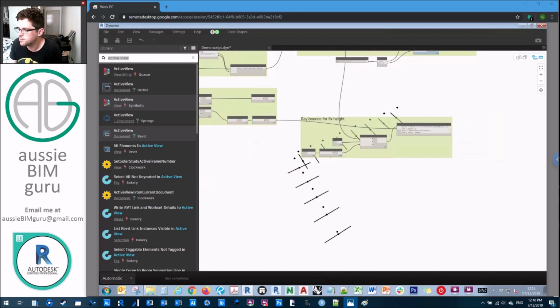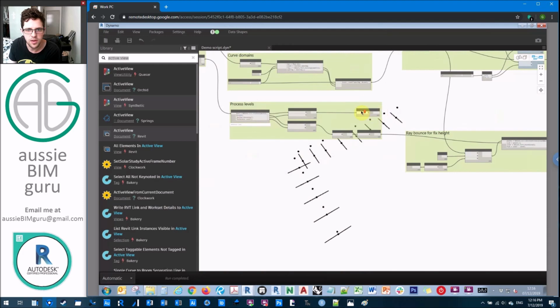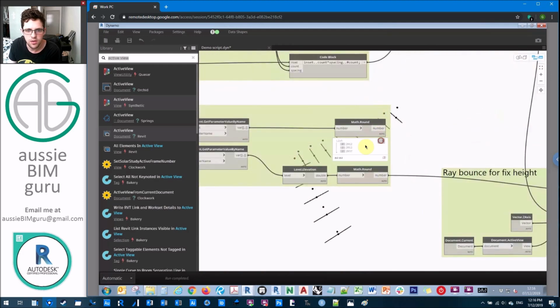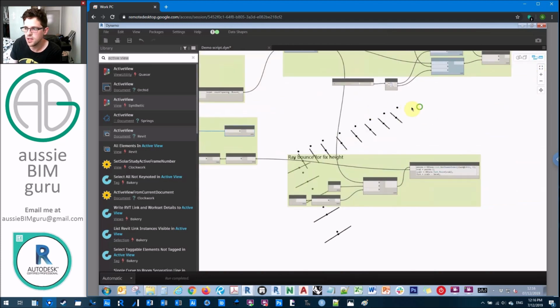The last thing we need to do is get the support height. In this case, this one's quite easy because we already have the support height technically. So we know the bottom of each duct run, but what we need to do is replicate this number for each support so that we can set the parameter at the equal list size when we get to the end.